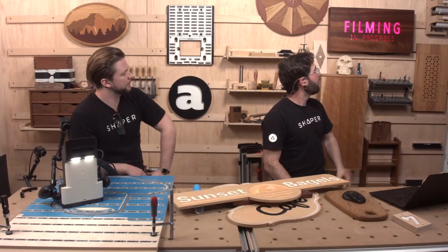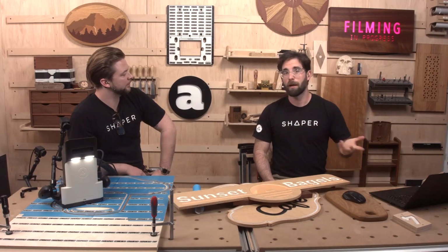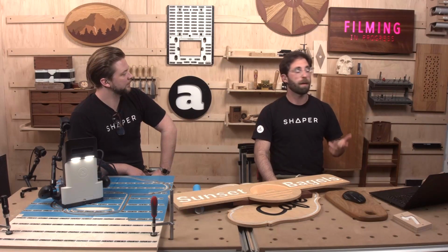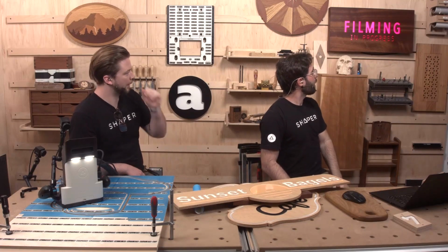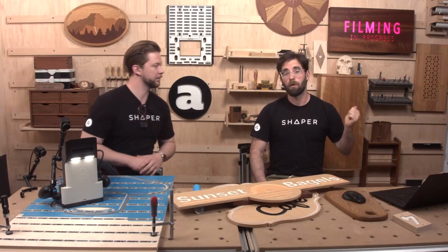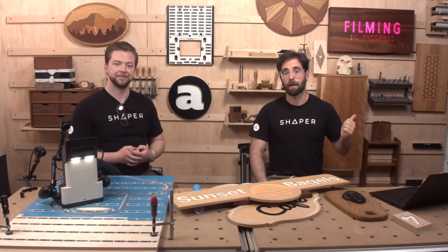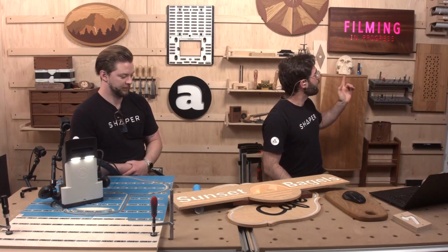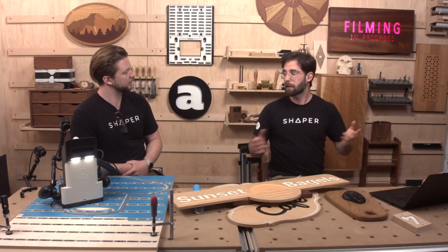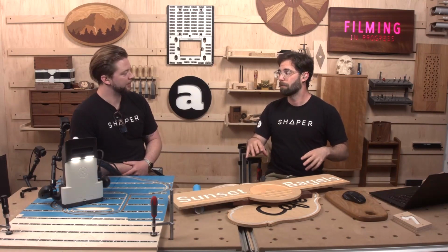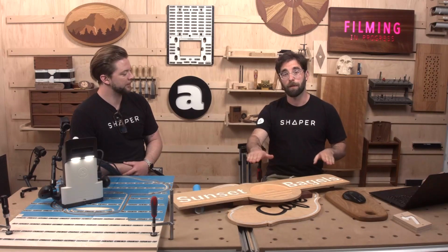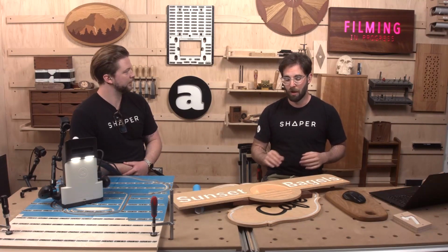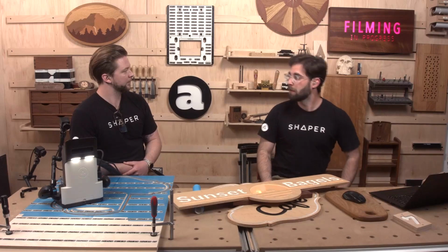And now this is really special because one thing about epoxy that you don't get with paint, and that you don't get with brass, obviously, is that it's transparent. So you can see the light coming out through that epoxy. We actually did a whole shape recession on this specific sign. So again, I'd recommend that you go watch that. But the interesting technique that I took away from this was that it was actually mirrored. It was cast upside down. Yeah. Right? And so that gives you a really good, flat, bubble-free surface at the base. We still had to sand it down a little bit to get it perfectly flush, but that gets you a nice, smooth surface of epoxy at the front of your sign.